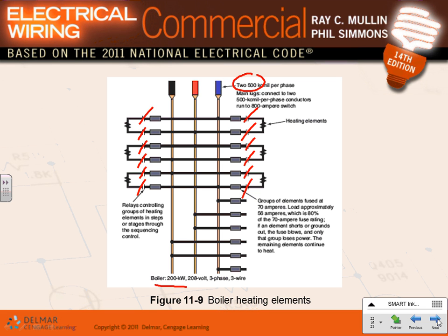Because there's a signal coming here asking for more heat, and these resistors that are burning right now are not enough to get you that heat, so they start closing more and more contactors, burning more and more resistors, or opening more and more contactors to burn less and less resistors. Can I have thumbs up, Chad? This is how these guys control an electric boiler.